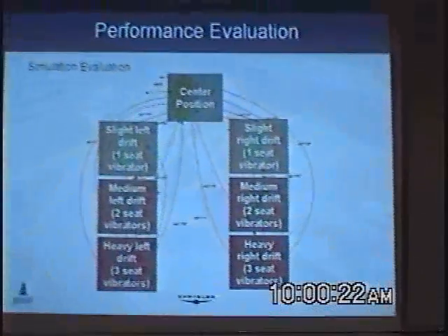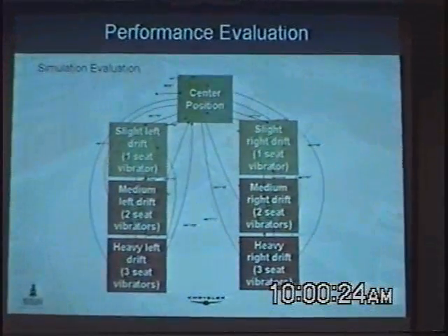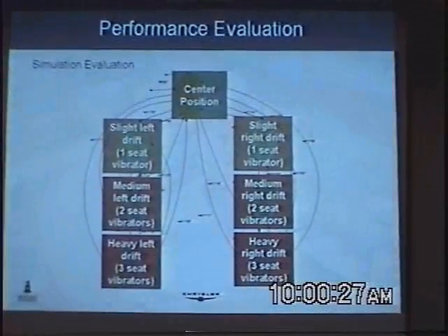Next, we used Xilinx and state-flow editing in Xilinx to come up with the states for the different scenarios: when you're in the middle, when you're drifting on the right side, and when you're drifting on the left side, and the different interactions with these scenarios, as you can see. We also used ModelSim to test 4 different scenarios: when you have different color lane markings, whether white or yellow, and when you have dashed or straight lane markings. Our system was able to do this. We used ModelSim to determine the incremental alert system, and our system gave us incremental alerts.